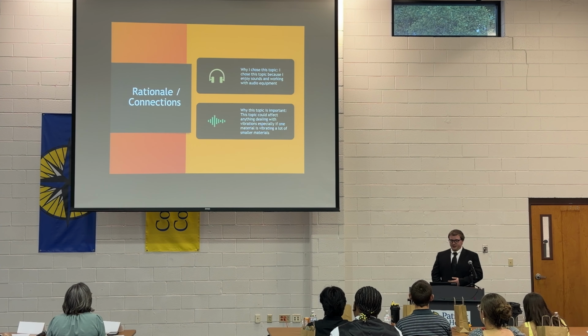So for my equipment for this experiment, I had to have an amplifier, a speaker, and a tone generator. I needed an amplifier because larger speakers need an amplifier to work at their rated frequencies, and this can be hard to achieve from just a headphone jack output. And the amplifier also would convert the output of my headphone jack into a speaker wire output, which allowed me to easily connect to any speaker I could buy online.